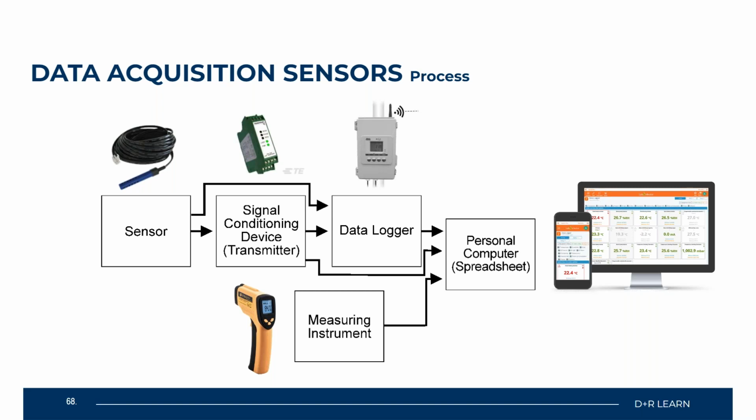sensor information all the way up to processing that information on your PC. So we understand what our sensor is, and it basically takes the measurements of your ambient zone temperatures, relative humidity percentages, and your air velocity. It also can detect smoke, pressure, and motion. So that is what your sensors are responsible for. And this little image here shows exactly what a sensor could look like. And this is one that fits in a well or some sort of a bored hole in chilled water piping.